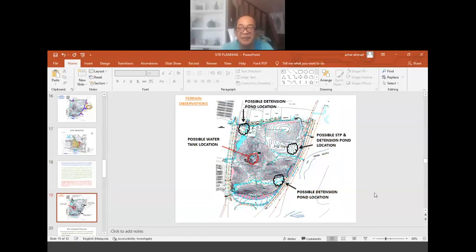This is our site analysis. Just now we had our site inventory. From the inventory information, we can say, okay, now we can possibly locate the water tank on this peak, which is the highest peak, 40 meters plus as we saw earlier. When we say we want to put our possible water tank location here, it means the existing level of 41 plus can be maintained.